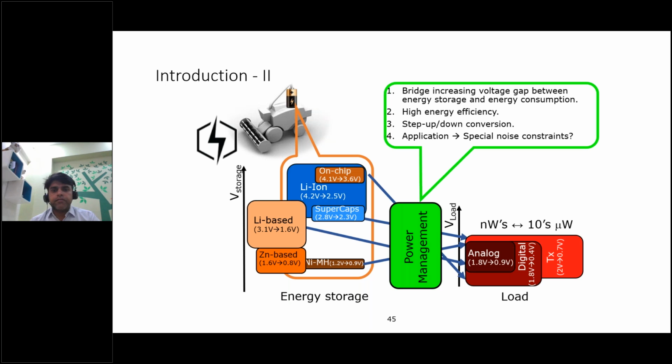If you really see the evolution in the chip industry, it's drastically changing. Technologies and power supplies in 2000 versus 2020 have changed ridiculously, and even from 2010 to 2020. For example, most of the analog which earlier worked on 3.6 volt, 5 volt now works on 1.8 volt, and in fact the majority works on 0.9 volt or even lower. Most of the digital has gone all the way from 1.8 volt to 0.4 volt.